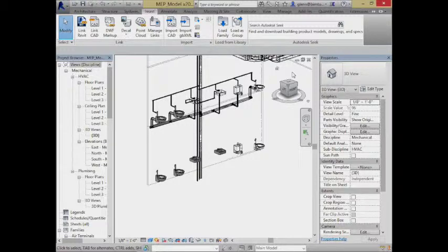Interestingly, we don't always have hot water supplied by a central system. In a lot of commercial applications, we'll have a little mini water heater just underneath the sink that's supplying the hot water as opposed to doing it from some central boiler. So we can go either way on that. Cold water at the sink, cold water feeding some sort of flush valve on each of these. There's a certain amount of flow for each of those, but that's the basics of the plumbing system. We have a certain number of outs, a certain number of ins, each with a certain capacity or flow it has to deliver, and as we work with the pipes, we lay it all out to deliver those.